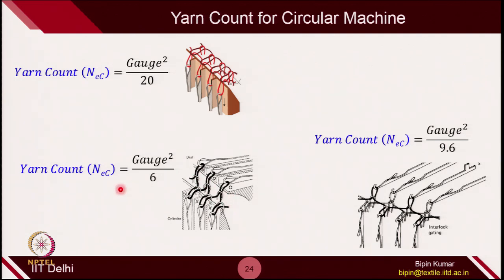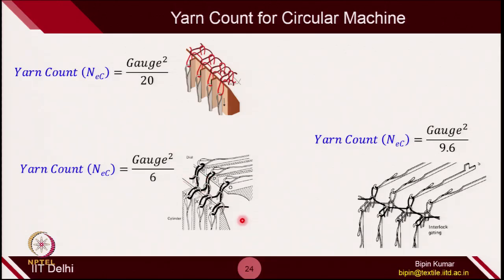That is why in rib and interlock machines the yarn diameter will always be lesser than that used on single bed machines, because whenever we are making double jersey fabric, because of the presence of the double bed, the available space for knitting is less. If you play with much thicker yarn here, there could be a lot of rubbing of the yarn, so there might be disturbance during knitting. So, single bed you can have higher diameter, but double bed you can have lower diameters.